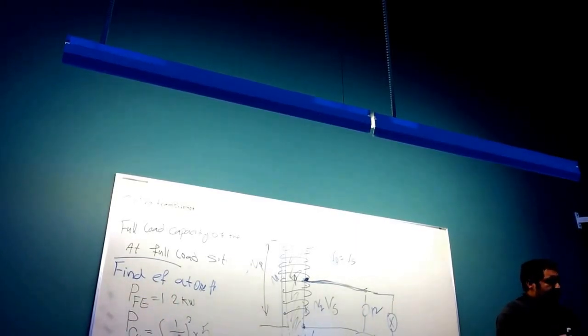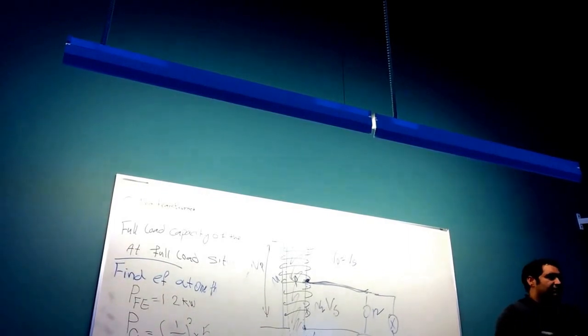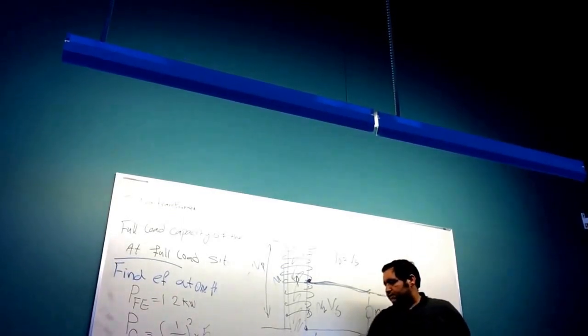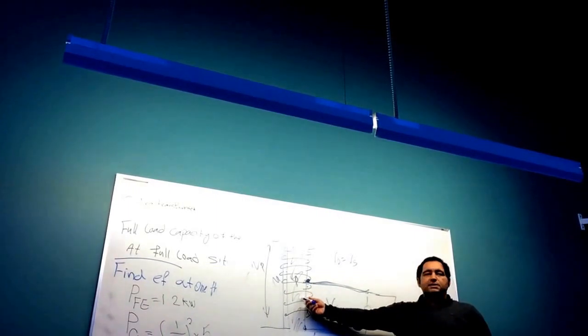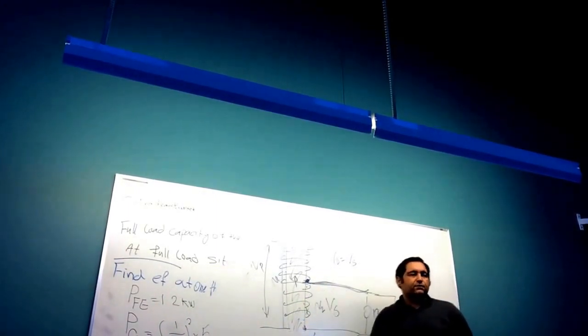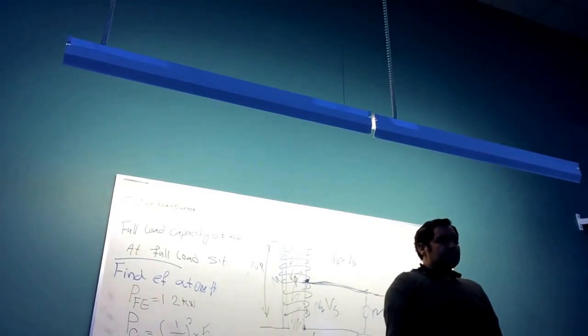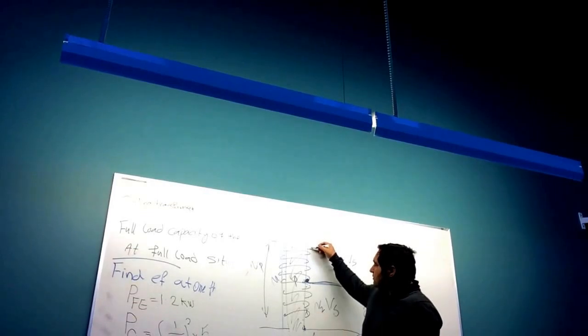The idea that I have is there is no connection between primary and secondary. Here we have a connection; here they are not isolated from each other. The transformer that you're saying, we call the double wound transformer. This transformer is a single wound transformer, or auto transformer. Yes. Now what happened to the current? The current is coming here.